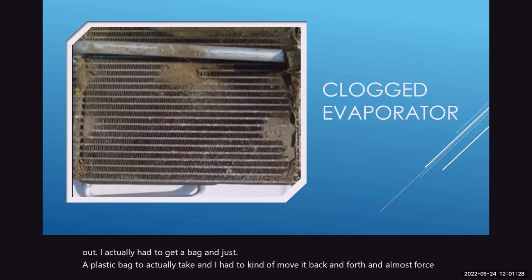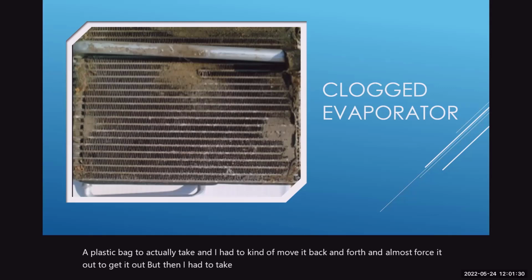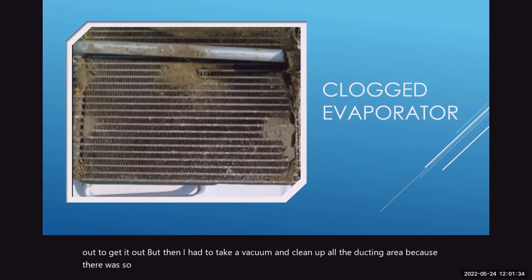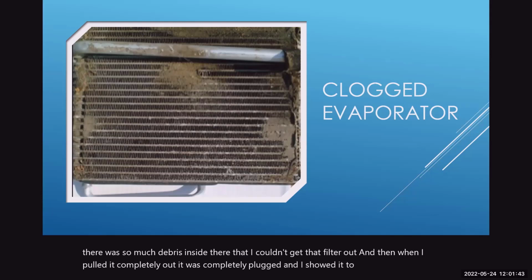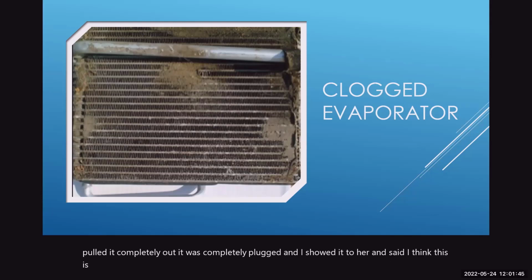Then I had to take a vacuum and clean up all the ducting area, because there was so much debris inside there that I couldn't get that filter out. And when I pulled it completely out, it was completely plugged. I showed it to her and said, I think this is your problem. So I went down to the local AutoZone and picked up one. They make them all kinds of different flavors, as I call it.